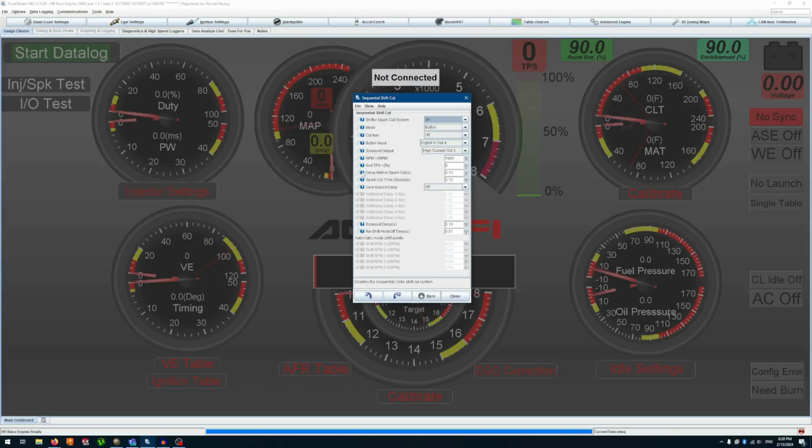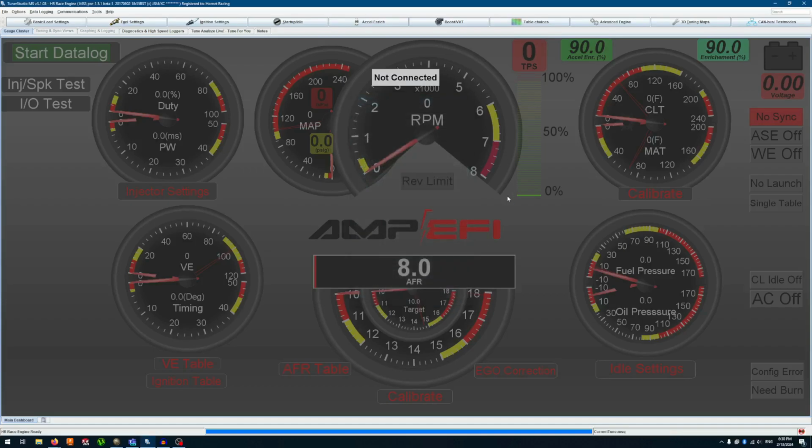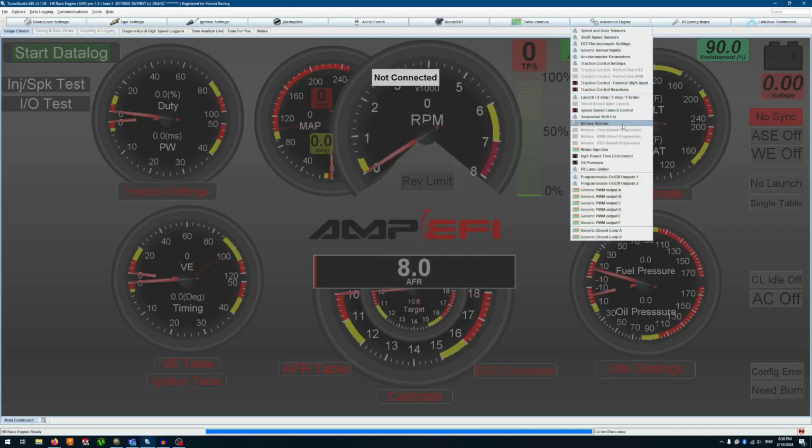then you shift, and then it cuts the spark for 100 milliseconds, and then it keeps the solenoid powered after the spark is returned. So it pressurizes, shifts, cuts timing, stops cutting timing, and then releases. That's sort of how you can think about it. You can set different delays for each gear. And then you can actually make this shift automatically if you really wanted to.